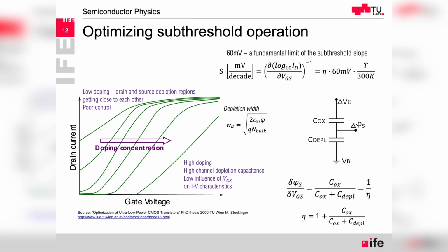And so what we can do to have a low depletion capacitance is, one thing, increase the body bias, so make a more negatively biased bulk, so lower for an NMOS transistor or higher for a PMOS transistor. Or there is a large play room with the doping level.